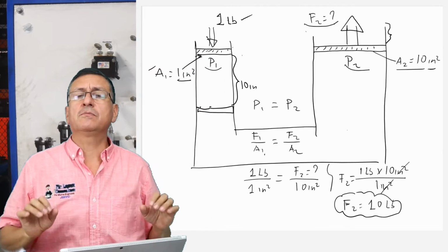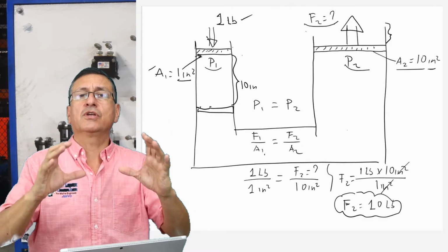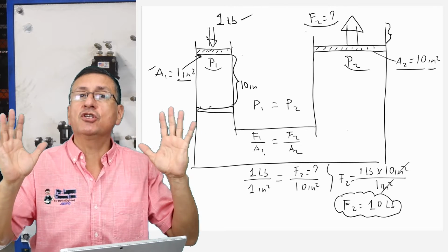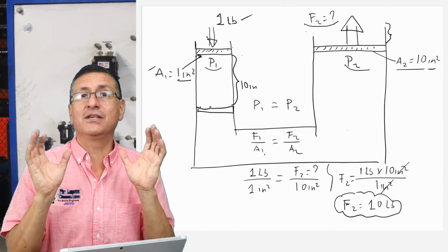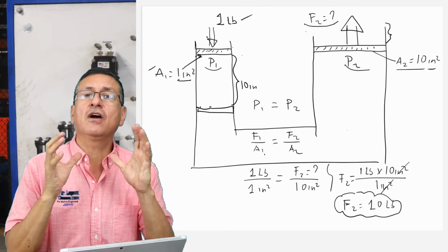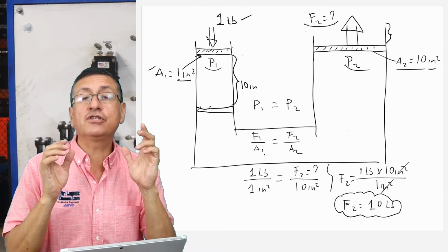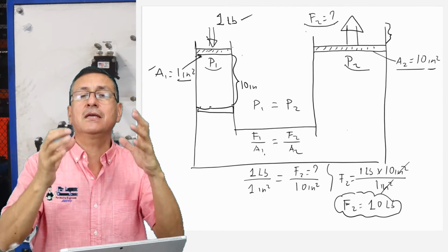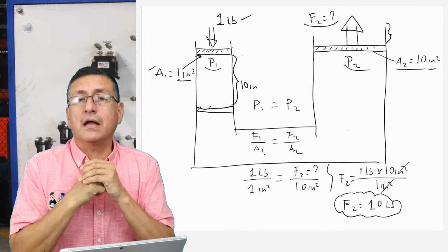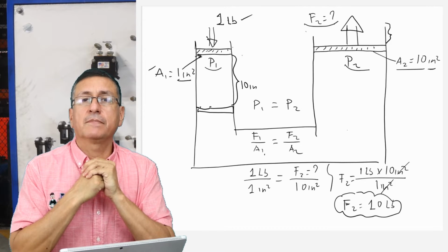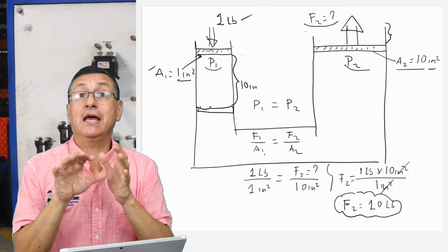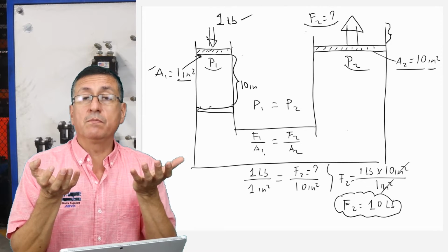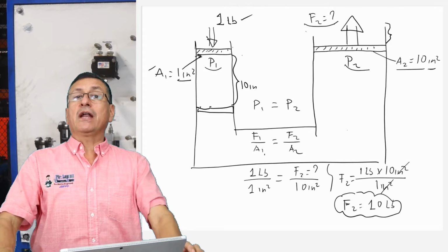Alright, my friends, when we mention hydraulic systems like the bow thrusters, like the actuator for the garage door, those systems are completely closed, hermetic. In those systems, the pressure should be constant, unless you have a leak. If you have a leak, the pressure is not constant because you have a drain, and air enters the system. Once again, in this system, the enemy is the air and the water, the humidity. But we are going to study later what happens if the oil is foaming with bubbles of air. Okay, we are going to continue.